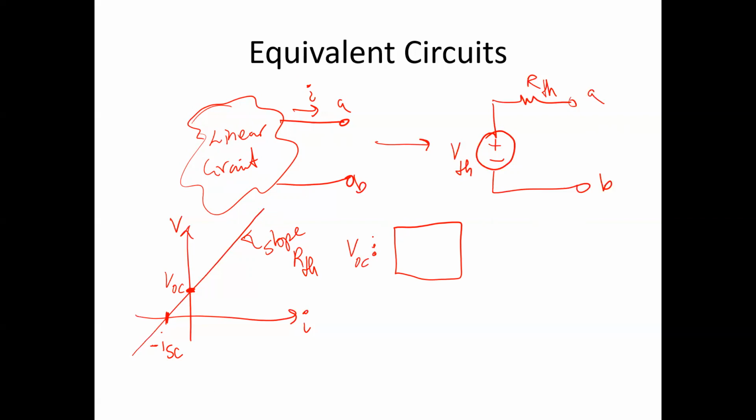If we actually wanted to measure this physically on a circuit, we would have to recreate open circuit conditions. So that would mean that we take the nodes A and B, and we make sure somehow that there's no current coming from our probes, of course, when we're measuring A and B. And under those circumstances, the voltage that we measure would be VOC.